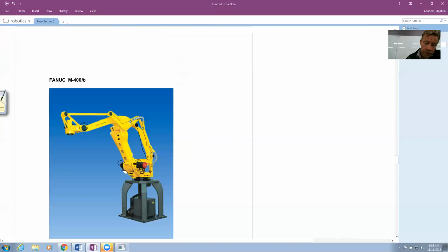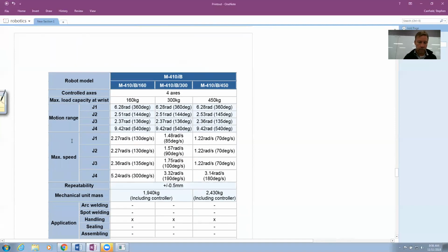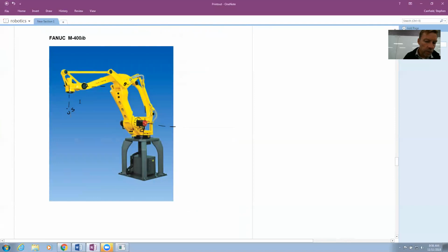However, for the purposes of our robot frame assignment, we're treating serial link mechanisms only. So in our analysis, we're not really treating these extra in-parallel links. So we have a revolute coming up, a revolute coming out here, a revolute coming out here, a revolute coming out here, and then a revolute coming out here. So this is 5 axes, and you would treat it in the normal way. Or 4. Maybe they're not even referring to joint 5, actually.